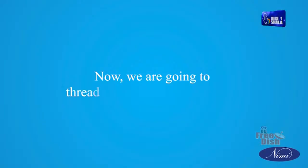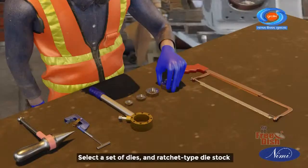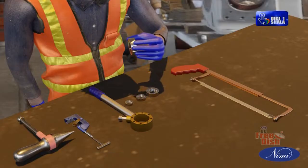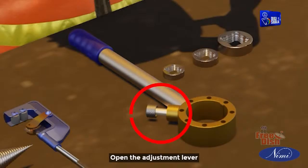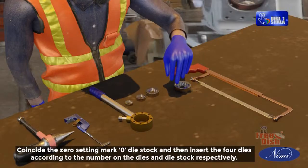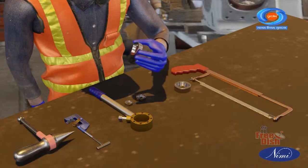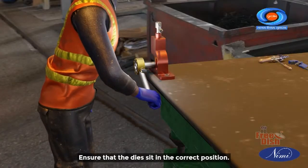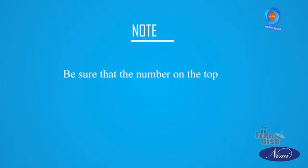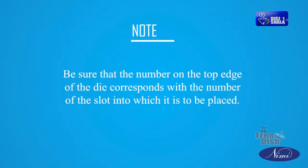Check that the pipe ends with tri-square for squareness. Now, we are going to thread GI pipes using die stocks. Select a set of dies and ratchet type die stock. Open the adjustment lever, coincide the 0 setting mark on the die stock, and then insert the 4 dies according to the number on the dies and die stock respectively. Ensure that the dies sit in the correct position. Note: be sure that the number on the top edge of the die corresponds with the number of the slot into which it is to be placed.